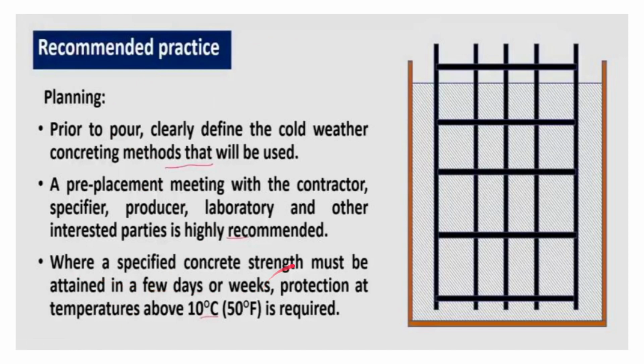And where a specified concrete strength must be attained in a few days or weeks, protection at temperatures above 10 degrees centigrade or 50 Fahrenheit is required. So if it is very important that the concrete strength should be gained at a specific time, days or weeks, we have to keep that temperature above 10 degrees. We have to install some techniques for that.